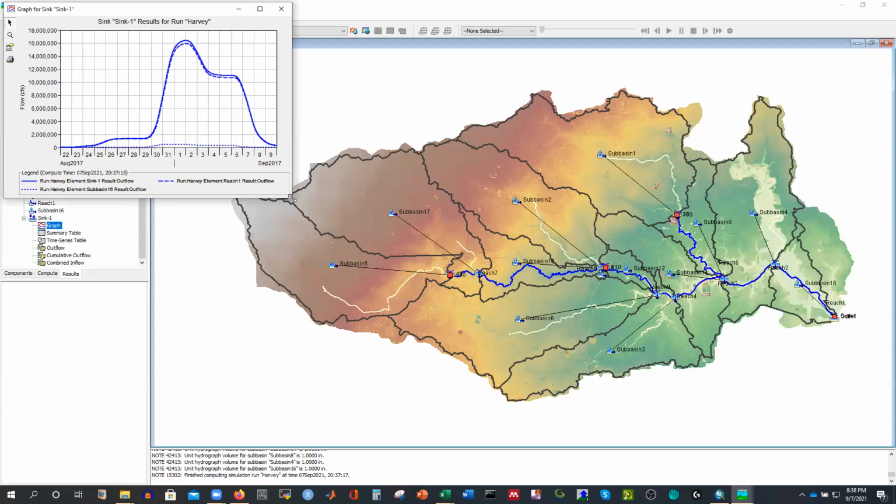If you follow my previous video on ArcGIS, I'm working on that specific region, so I downloaded every possible data. I have the rainfall data, rainfall locations, the USGS stations, everything, and I also downloaded the DEM. How to download this DEM, I already uploaded the link. You can click that link, and I already demonstrated how to download the DEM, how to extract it for this study area, how to project it from WGS to state plane, and how to change the vertical unit from meter to feet. I already mentioned everything. If you are interested, you can check the previous videos.